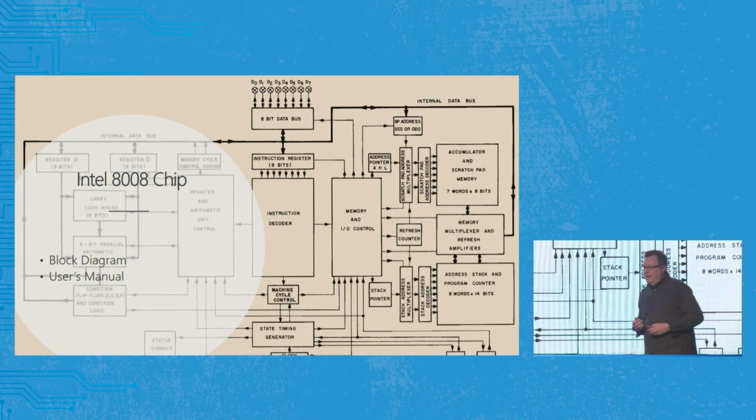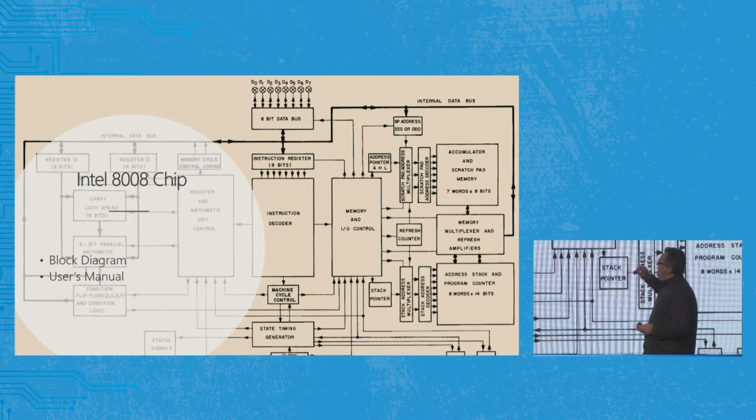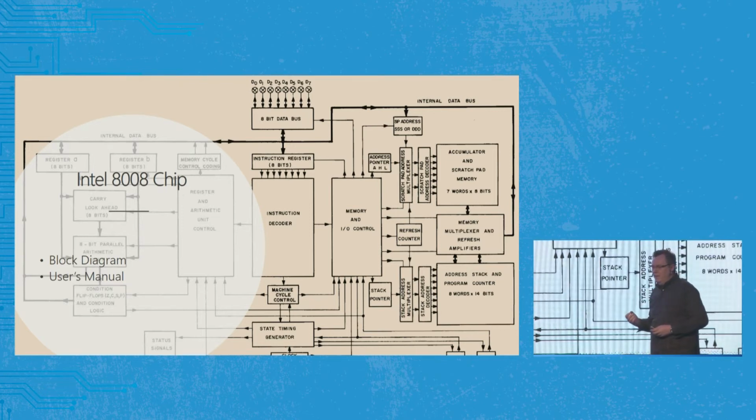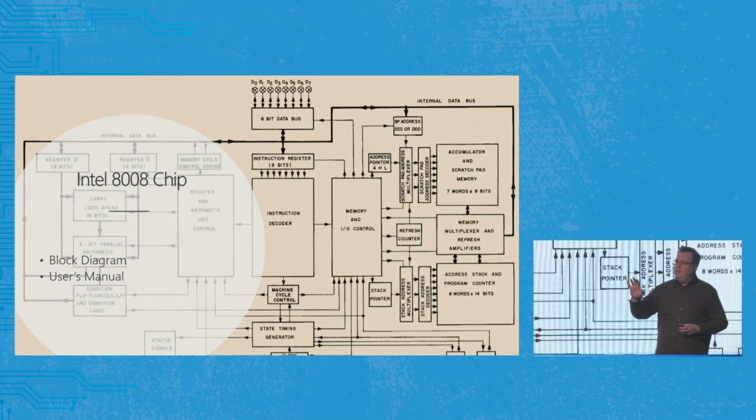Another aspect of looking at these chips is the diagram of how they are supposed to operate. In many ways, you look at this as a block diagram, and there are a lot of things happening on the processor. When it comes to reverse engineering and understanding the secrets, how do I go from that metal layer into this block diagram? For example, if part of the block diagram is a cryptographic routine, I have data stored on this chip or in memory, and it's encrypted. I have a cryptographic routine, I have a secret, and then I have the data output. Can I figure out a way of bypassing all the cryptographic routines to get to the secrets themselves?